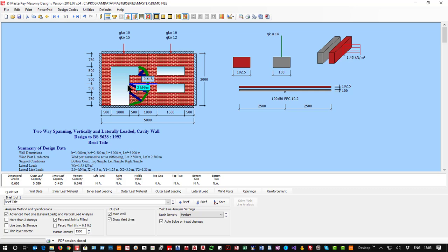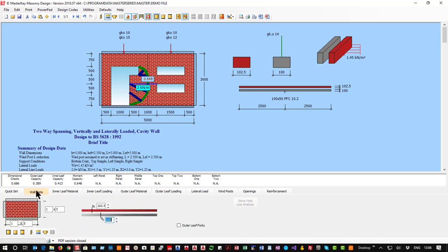And some people say to me, why horizontal line loads? Well, sometimes if you've got a racking system, you're going to have wall loads attached to the wall to stabilize your rack, or even barriers for crowds and things like that can produce a line load onto the wall at 1.5 meters high and things like that. So this is where we're going to get to eventually, but let us just start by taking a brand new wall,